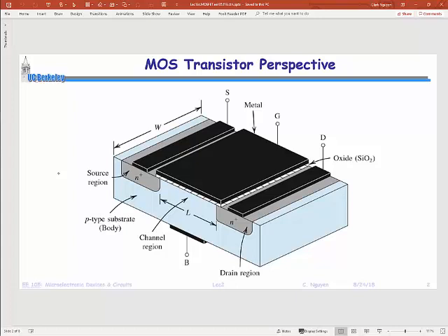I also have what's being called metal right here, but oftentimes this gate is not metal. For the longest time, this is called the gate. That's what the G stands for. And that gate has for the longest time been polysilicon. The reason for that is I can grow polysilicon over oxide, which is what this hash line is right here, without creating too many interface states that would ruin the performance of the device. These are things that you would learn more in 130 and 143. But historically, this has always been called metal.